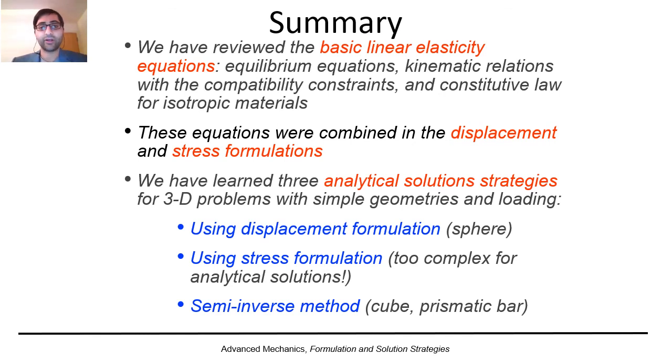We have learned 3 analytical solution strategies for 3D problems with simple geometries and loadings: using displacement formulation for a sphere problem, using a stress formulation, which was too complex, so we didn't do anything with it, and using the semi-inverse method for a cube and a prismatic bar under simple loading.